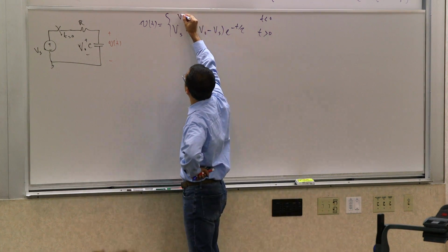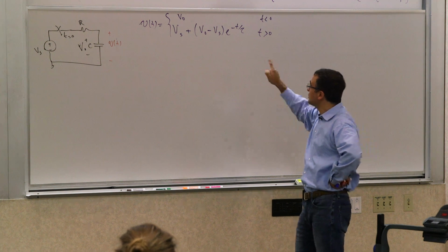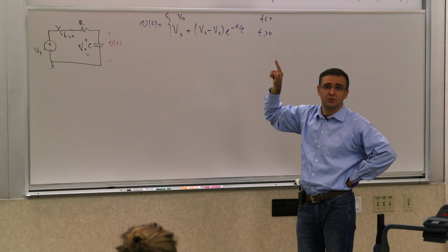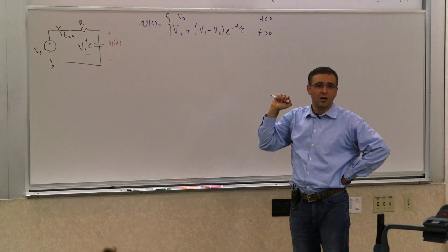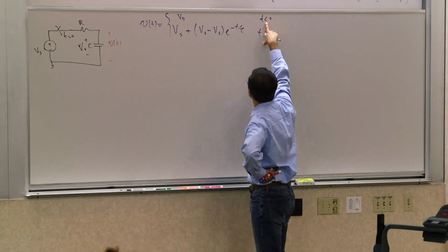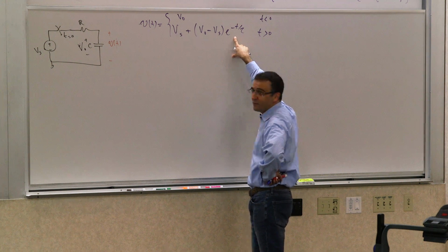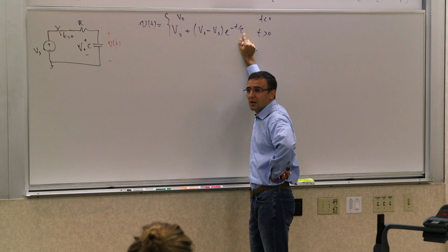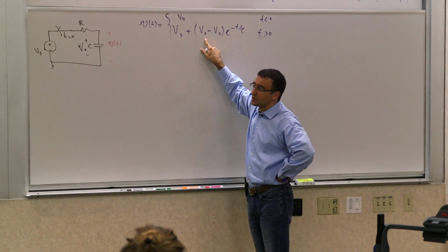V0. And you can see, actually, what we know is that it shouldn't change from t equals 0 negative to 0 positive, right? 0 minus to 0 plus. Does it? Let's see. At t equals 0 minus it is V0. And at 0 plus, if I set t to 0, what happens? What is e to the power of 0? 1. So Vs cancels negative Vs, and then I'm left with V0. So it's continuous in that sense.